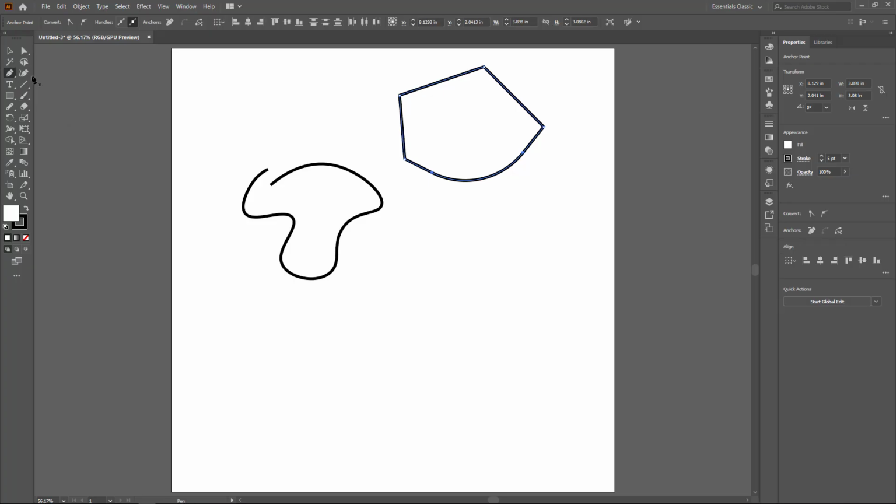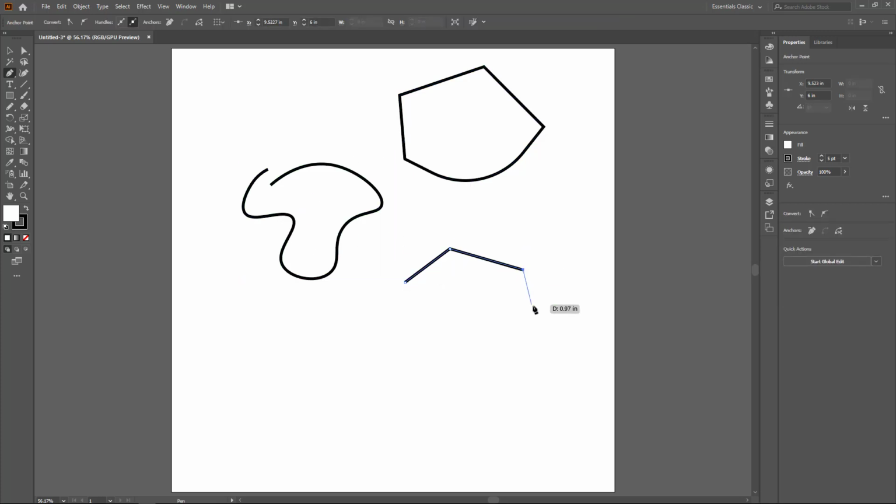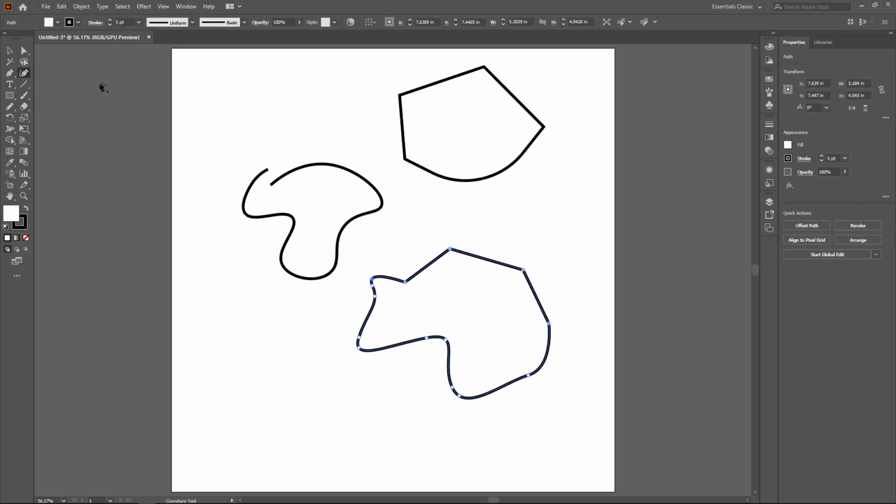Now, a dirty little secret about both of these tools is that they can actually become the other tool pretty easily. Normally, when I'm drawing with the pen tool, it just draws segments. If I click and drag with the pen tool, it becomes the curvature tool. Same with the curvature tool. If I'm clicking along happily, drawing my Bezier anchor points, and then I hold down Alt, it will start to draw straight lines. And moving back to your original starting point will close this loop.